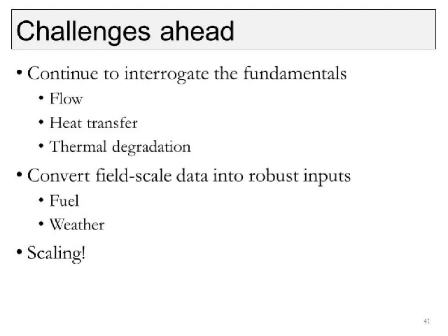I don't have the exact figure in front of me, but we're sampling at 10 hertz, and that's definitely coarser than the actual response time of the pressure sensor. And we just have it connected to some static pressure taps along the length of the test section, as well as to a pitot tube to measure the velocity that is associated with a particular pressure drop.